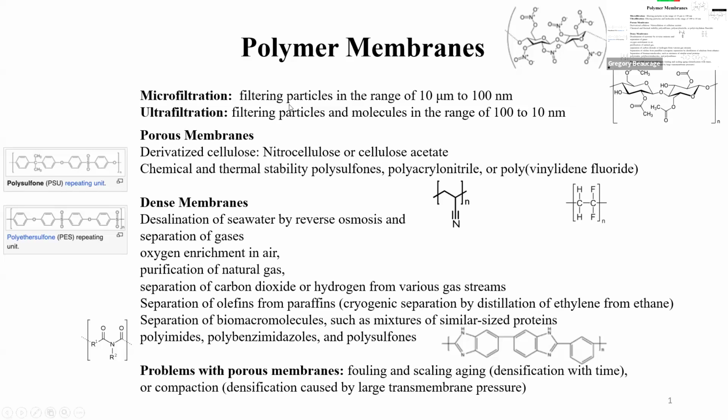Again, it's engineering, just how to design it so that you have really small fibrous membranes, or rolled films, so you can have everything really tiny, so that you can withstand high pressures. The high pressures can drive whatever you want to do, such as microfiltration. Depending on what range you're in of the size of the pores, there are different kinds of separation that are going to go on.